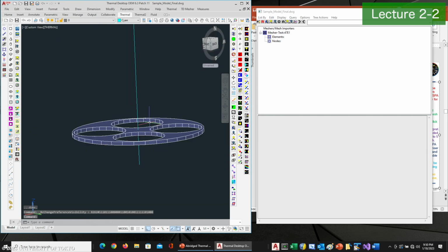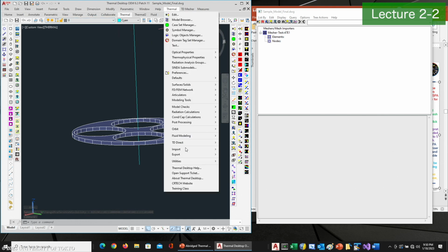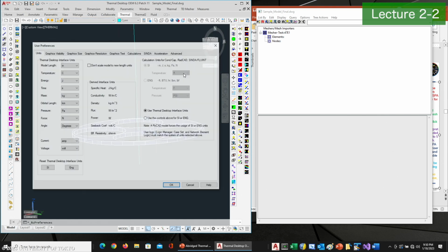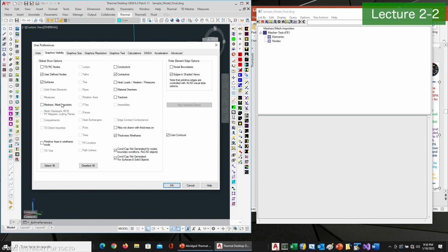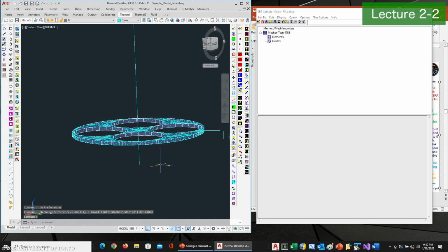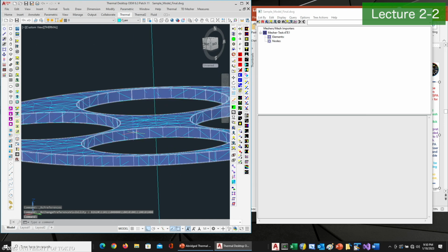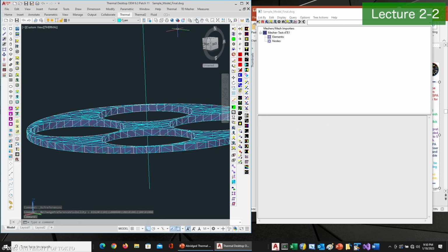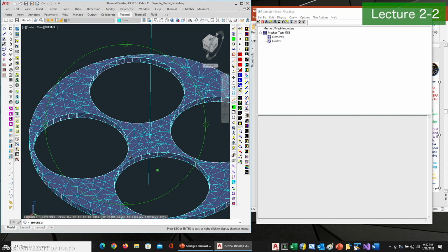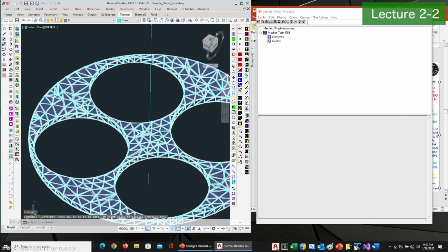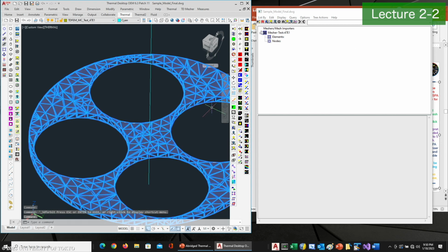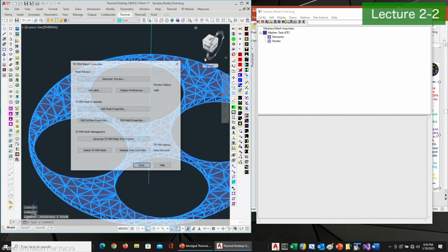And it should be showing me the differences. Here we go. I got to turn on meshes and mesh importers. Yeah, it's kind of a quirk. It'll do that automatically. All right, so here you can see this is the mesh it created with a size of 3 inches for the one.